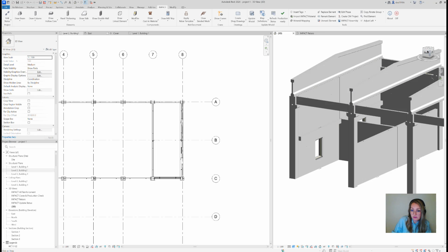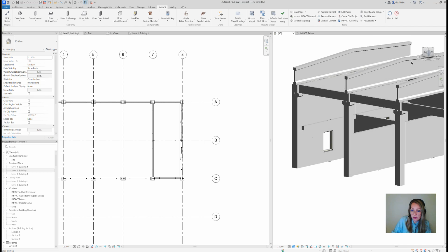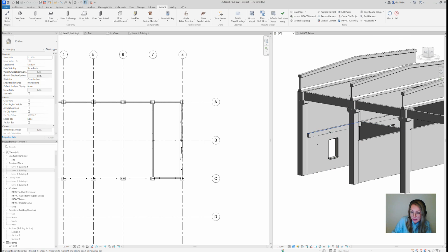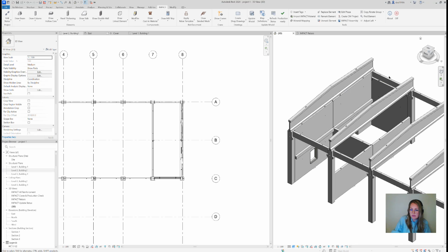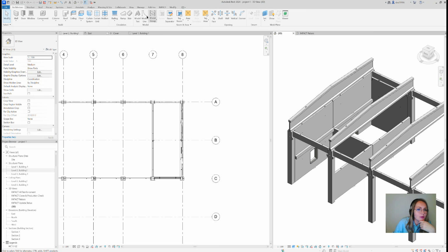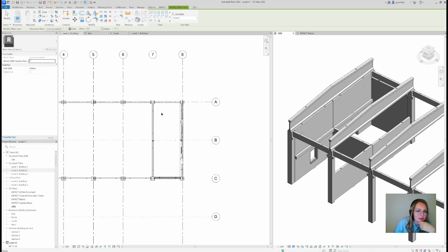As you can guess, we've done the panel thickenings because we want to lay down our slabs on the panel thickenings and on the massive wall and here. So I'm going to draw now the polyline. Okay, that's an AutoCAD language, but it's the model line. Sorry, it's the model line.